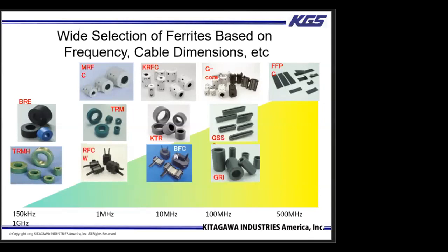Any more questions? I have one question. As the ferrites get heated, will the temperature degrade the performance? The temperature from the ferrite core itself? Yes. And how about the external temperature effects also? Usually, all ferrite cores will saturate if they reach pretty high temperatures.